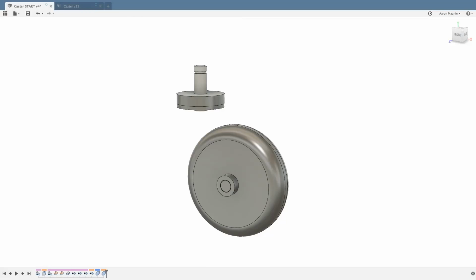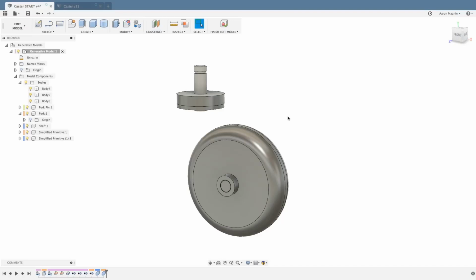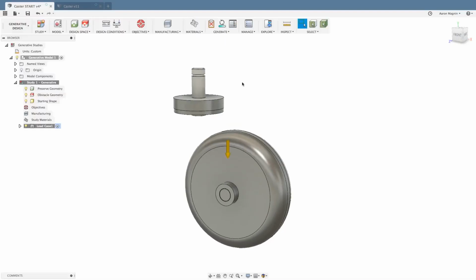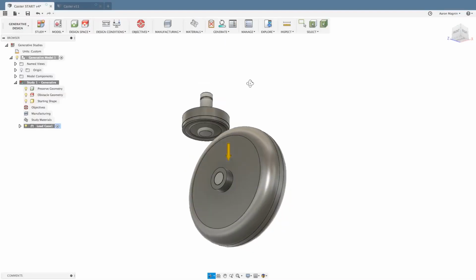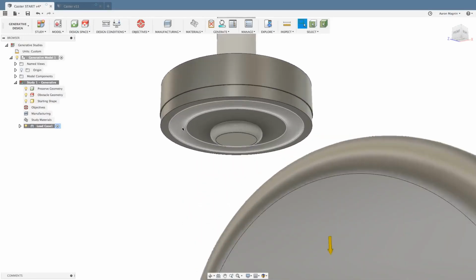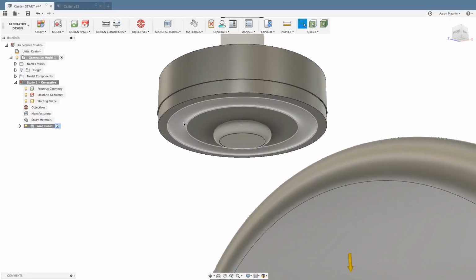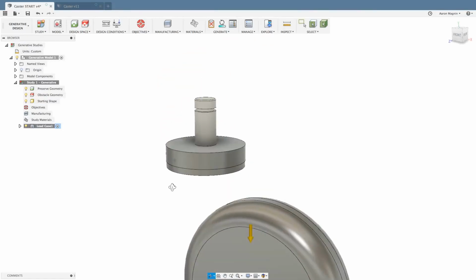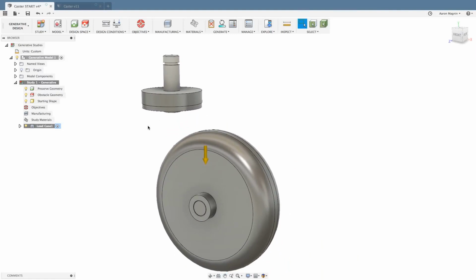So I'm going to check comments once again just to make sure we're good. Looks like we're good. So with that, we'll go ahead and finish the edit portion of this, and then we can start to move on to the next steps. One thing that I could have actually done too is I could have just deleted this face when I offset the groove for the ball bearings, the balls for the bearing. It creates a groove on the bottom, obviously, because that's the way it was offset. If you wanted to, you could just select this and delete it with our cool and powerful deletion methods that we can use, but not a big worry for me. It's not going to affect my results too much.